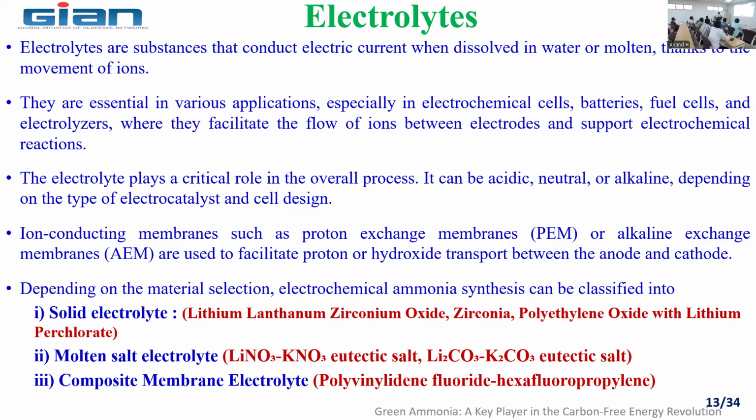So for the material selection of the catalyst, you need to go through different catalysis studies, like finding out the operating temperature. For doing so, you need to do the TGA, thermogravimetric analysis, to find the optimum operating temperature at which the catalyst behaves well. Because ultimately, if you add 1 kg of catalyst into the reactor, it should not burn. After several years of trial, I don't want the catalyst to be underutilized. I want the same amount after several years.